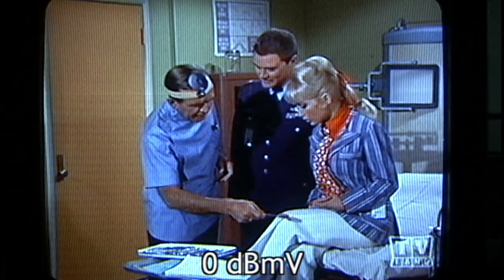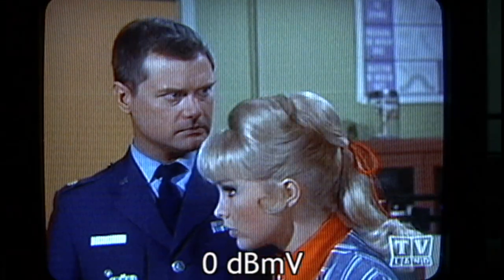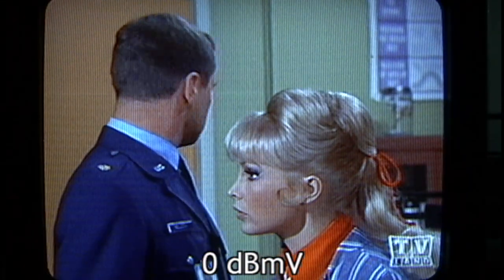Now, the only upper limit given in Part 76 is, I quote, a maximum signal level such that signal degradation due to overload of the subscriber's receiver does not occur, or something like that. Now that's usually a maximum of plus 15 dBmV, and ideally in the range of 0 to plus 10 dBmV. This is also the range that the cable tuners in televisions are designed to handle.